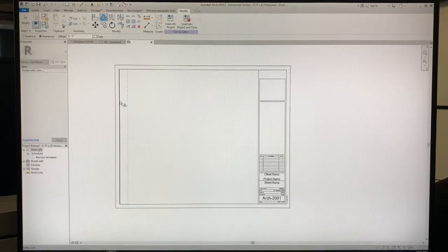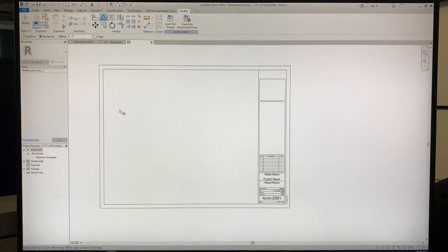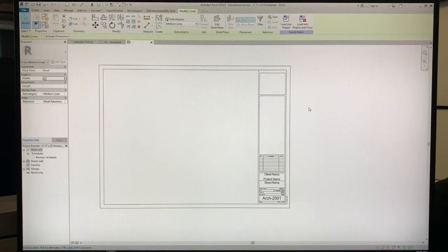And then the side, I want to offset 2 inches to make it a 24. So now change our offset distance to 2 inches. And let's go ahead and offset it outwards, or to the left. I always like to offset to the left and upwards rather than going this way, so that I don't have to move my title block. Press Escape now. And I'm just going to move this square right here. I'm just going to use my arrow keys to nudge it upwards, to fill in that space.